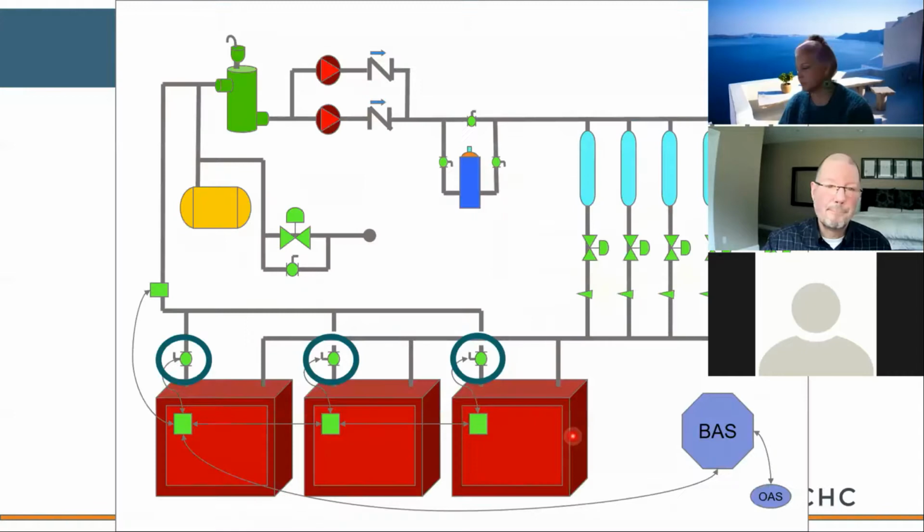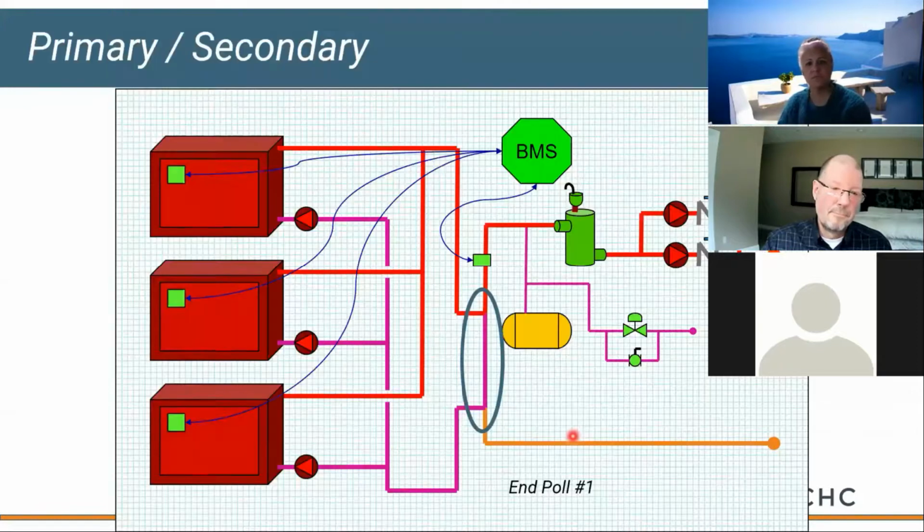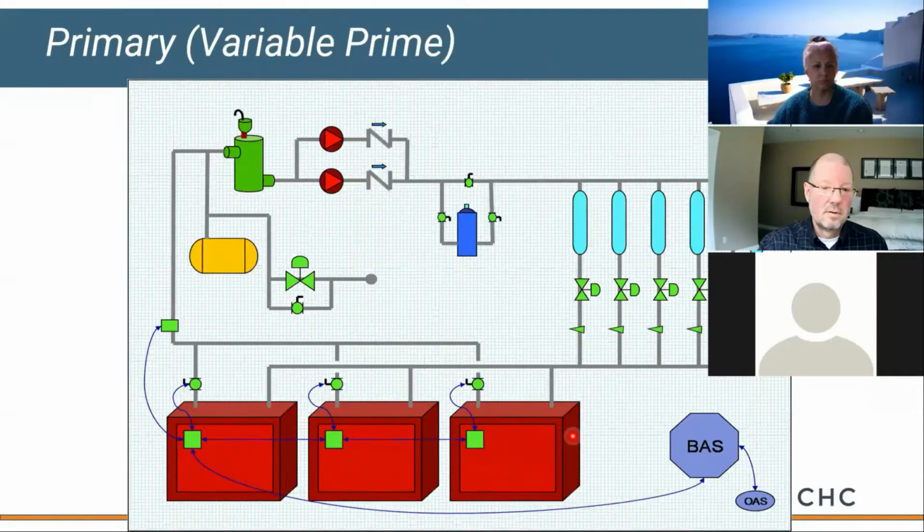So it's actually a chiller system, and the chillers are redundant almost, but 10% of the time the load gets high enough where a second chiller might be used in the system. And so currently we just have a primary loop, but I'm wondering if a secondary loop would be necessary for this through the chillers or even cooling towers that I have.